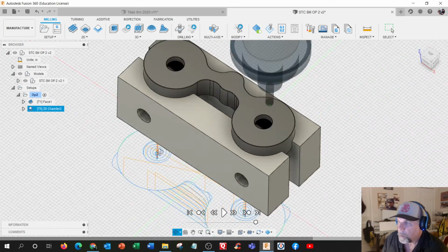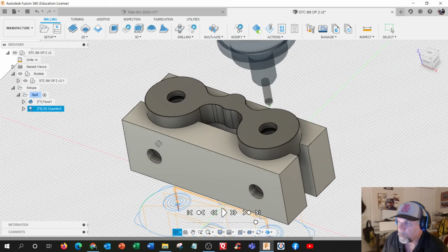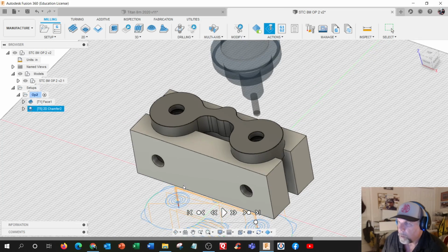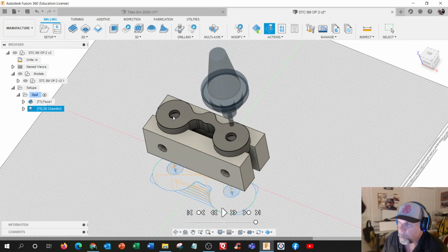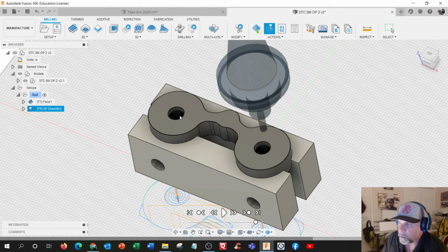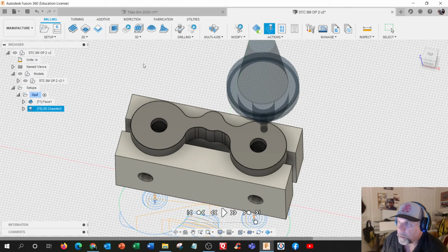Okay. So this is our soft jaws setup. And I'll probably even add the vise setup. So if we pre-drill the hole deep, so it pokes through the bottom, we take the probe and probe the inside of this. That'll get us our XY, and we probe the bottom of this, that'll get us our Z. The other thing I may do is add in a setup sheet.